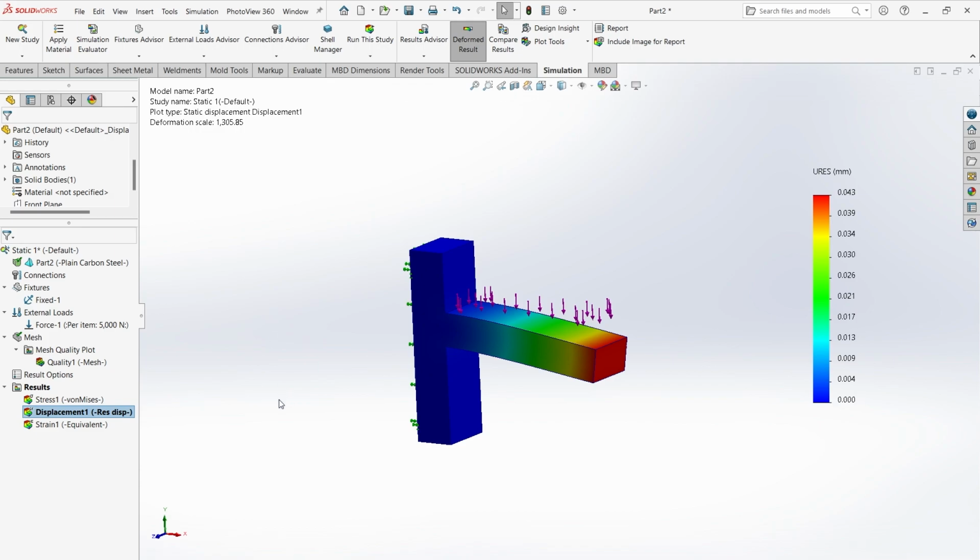Okay. Now another way, so from the displacement itself, we are able to visualize that this material is good enough to handle this kind of force. The second thing, the scientific term which is able to tell us whether the geometry is safe or not, is called factor of safety. Okay, so if the value of the factor of safety is above 1 or 1.5, then the material is safe to withstand the given force.